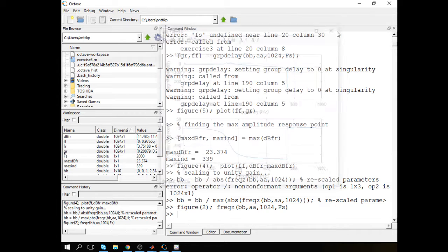Good. Okay. So all kind of stuff done for the system. Impulse response, frequency response, scale the frequency response, looking at the zero pole plane, amplitude response, group delay, that kind of stuff. So that's basically the whole thing about this filter analysis. The next step would be actually to go to the quantization effect of the filter coefficients. Unfortunately, the time does not allow me to do it.